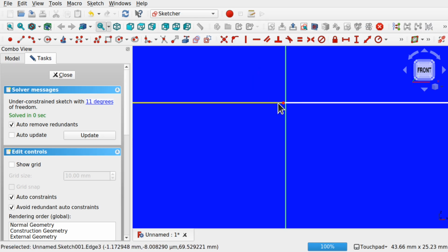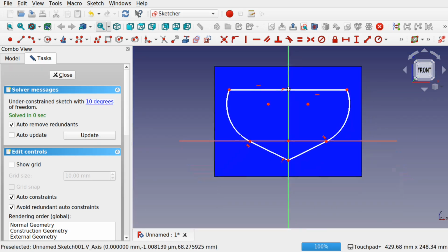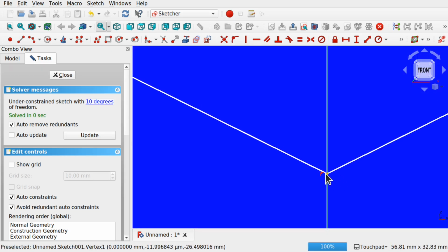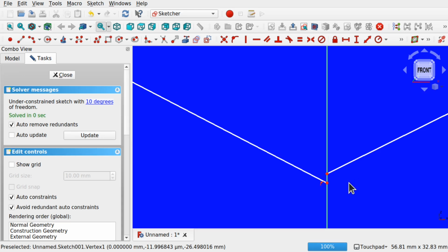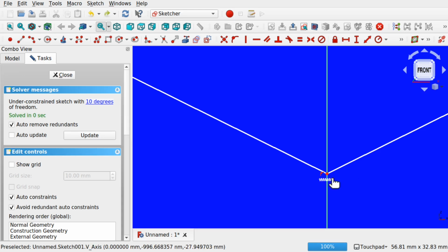This is offline from the center. Click that, click the center line, and use the point on object constraint there, this one here. Let's place it on there. We need to do the same for the bottom, because if we pull one of these out, you can see how they move. Control Z that and just highlight those two. Those two are highlighted. I use box selection around there. None of these lines have highlighted, so I'm all good.